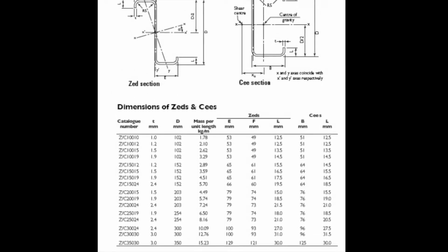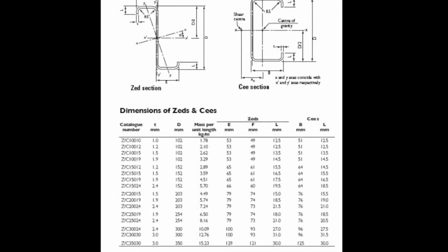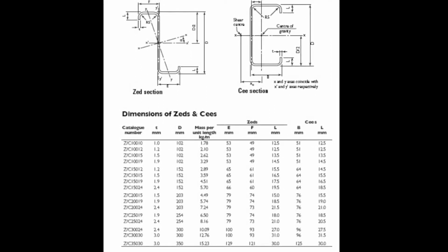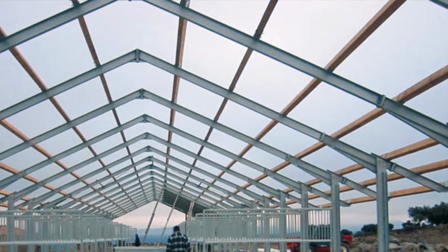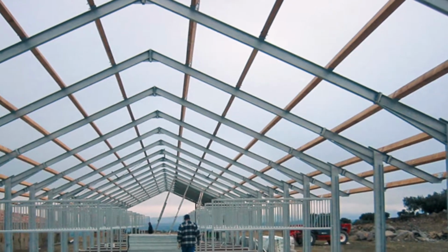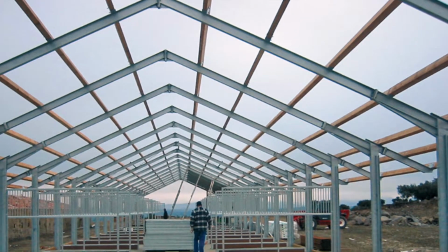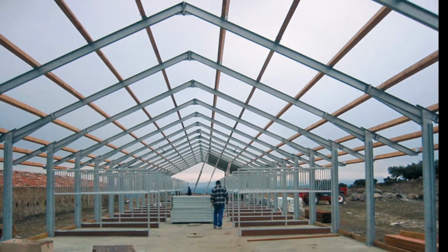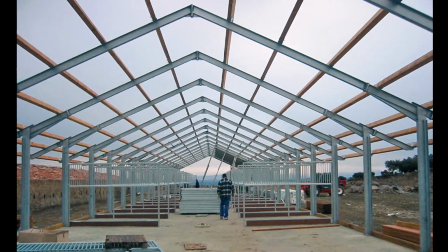For the wall sheeting material in particular, a section of ZC224 was sufficient. After designing the purlins and girts, we were then able to design the rafters and bracing of the structure, which helped carry the self-weight of the purlins and roof sheeting, along with helping send the loads to the footings through compression and tension.